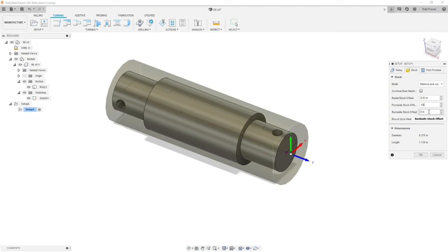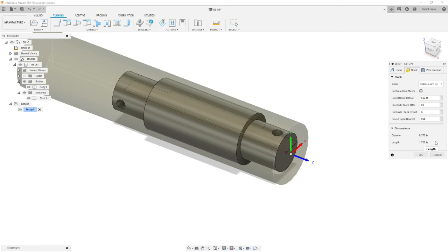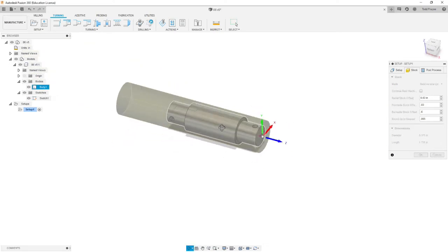And on the back side we need to hold on to something. Now we have 400 thousandths in front of the chuck, so if we're going to have the chuck hold on to about 1/2 inch, we need to put in 0.6 there. So when we go to cut stock, we need stock that's an inch, 0.3735 by 3/8 in diameter to make this part.